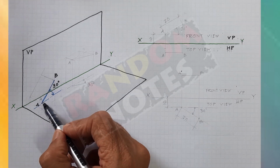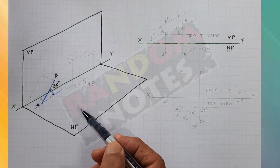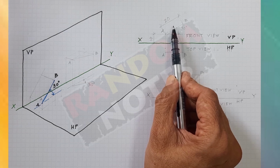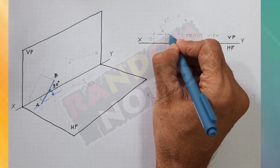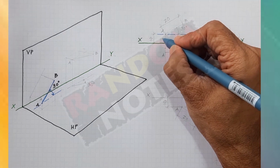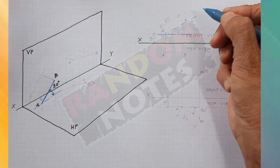So our line is at an angle of 30 degrees from the horizontal plane. This condition will get projected on the vertical plane, therefore it will be visible on the vertical plane. What I would do is make a rough line out here, take a point and draw a line at 30 degrees.